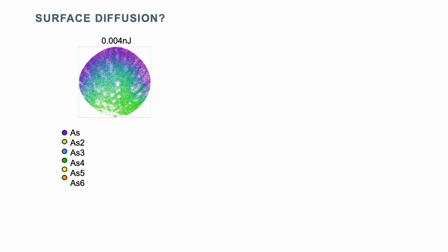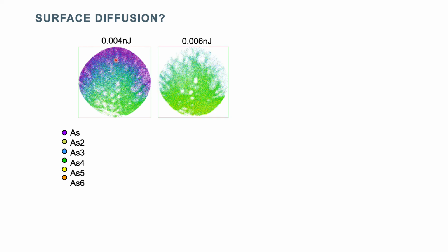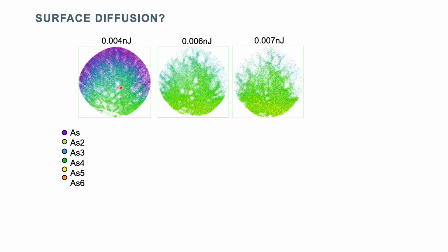Finally, an aspect of laser pulse evaporation that is not always straightforward to interpret. This is an analysis of gallium arsenide from Emmanuel Marquis, and we can see that there is a distribution in the size of the molecular ions that we are detecting, with smaller ones on one side and larger ones on the other, and this is because there is a range of temperature across the specimen surface. But as we start increasing the laser pulsing energy, this distribution changes, and we have these sort of weird gaps in the data that might actually just be coming from